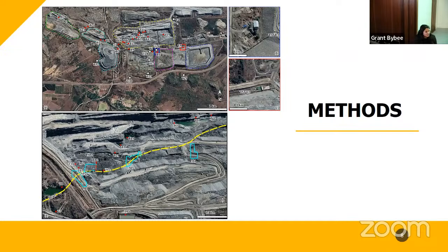Definitely a lot of fractures that are associated between the pits. The actual pits, again, remember, you're still going to have better resolution with the ground geophysical surveys, but we do have more fracture networks that are correlating the pits themselves as well as outside the mine. So that's also why we wanted to conduct our MASW, our seismic surveys, to see if we can correlate those higher resolution fractures with our regional aeromagnetic studies.